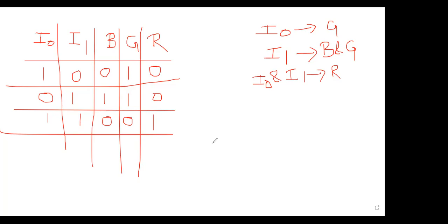Vilas sir, we have three outputs. So we should have only three output coils. You have taken four. You are relating one output with another. You don't relate, keep them separate. Like for green, you have tried. Green is getting on twice. So first you finish for green, then you go for blue, then you go for red. So separately we have to make. You're trying well, very good.